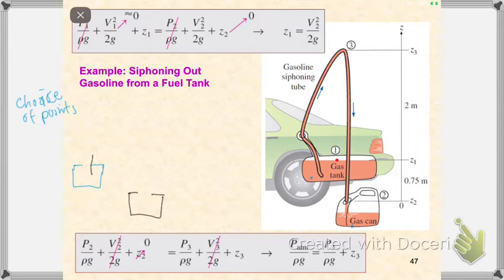Between these two tanks you have the pipe. That is the diagram. So here you have the water level, and here is your water level. Again, important things: choose your points wisely. In this case, we can build the Bernoulli equation between the water surface there, point number 1, and the liquid surface there, which is point number 2, which would be easier. So if we build the Bernoulli equation between these 2 points, what will happen? That is our Bernoulli equation.